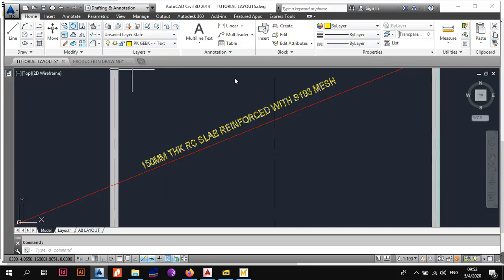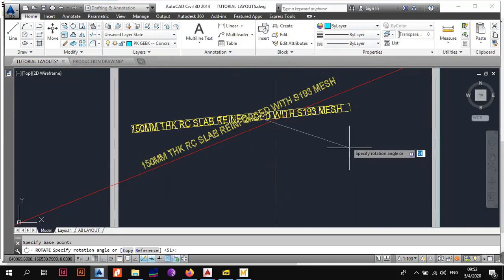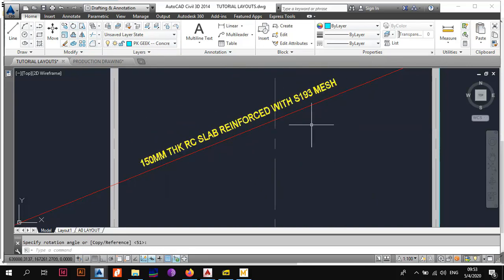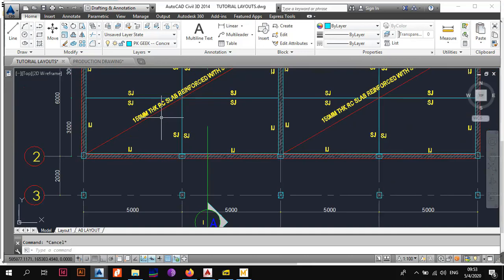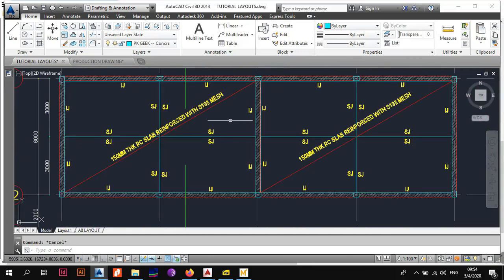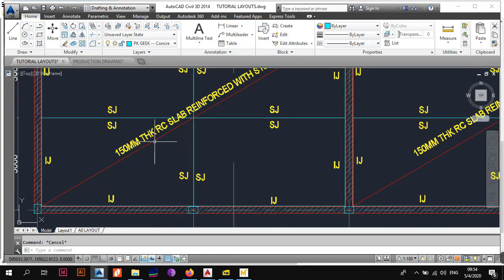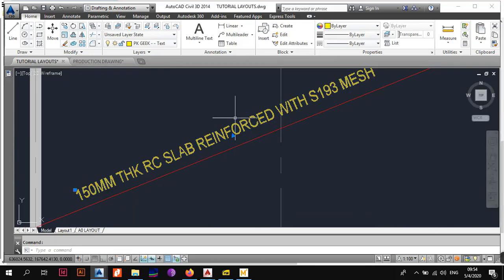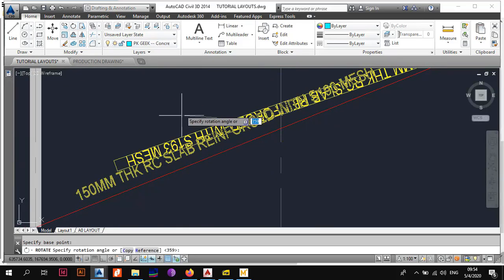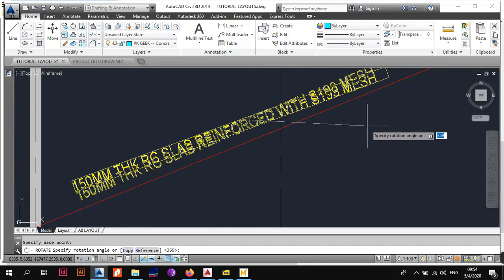And in this case now, this is not going to be a 150mm thick slab because it's different. This time we need to size the slab. The ground floor slab, why we just took 150, that was the minimum ground slab, and also because this area is just going to be a classroom without too many loads that are going to be on it, so we just decided to do a 150mm thick slab. But now what we have to do is now size the slab, and to do that we now have to do a preliminary calculation design to size the slab.